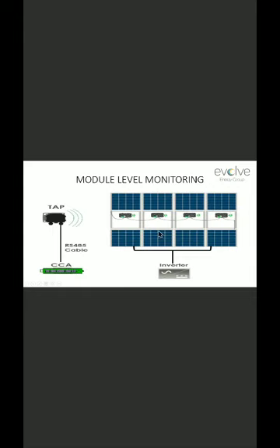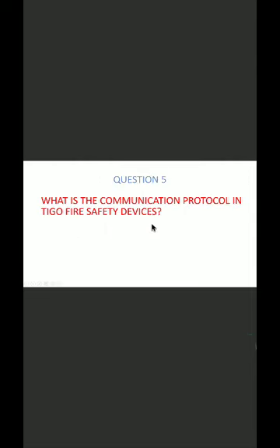We can get the DC data, and we can achieve the rapid shutdown feature with these two devices. Without them, we can't achieve rapid shutdown with AC disconnect, because something has to command it. Otherwise, over voltage, over current, and over temperature are handled by the self-decision of the optimizer itself, with no other devices.